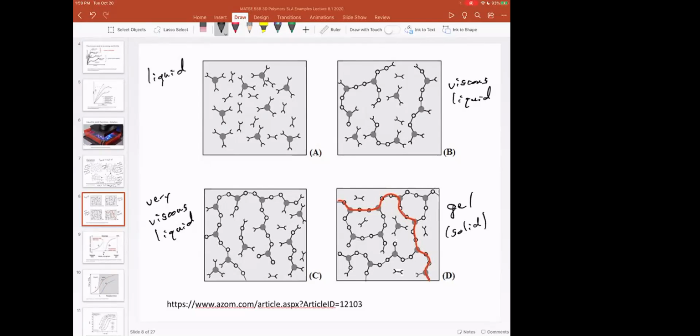And so it's a big challenge to make a resin that prints fast, but is still stable. Okay, makes sense. So when you get low resolution prints, or you get light bleeding, or you get resin curing in your material, or resin curing in the bottle, this exact reaction is happening, just the resin's too sensitive. So if you make a resin that's too reactive, you have uncontrolled reactions, because any reaction that happens using photochemistry in general can also occur thermally.